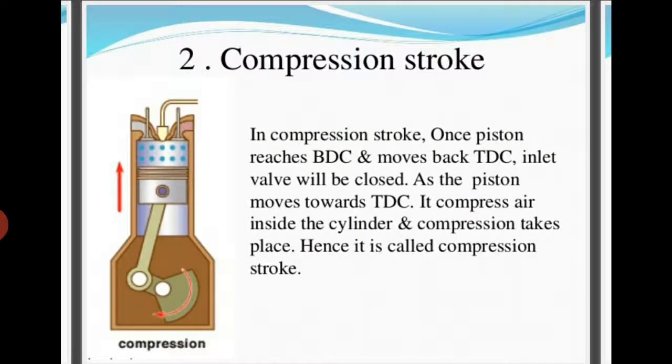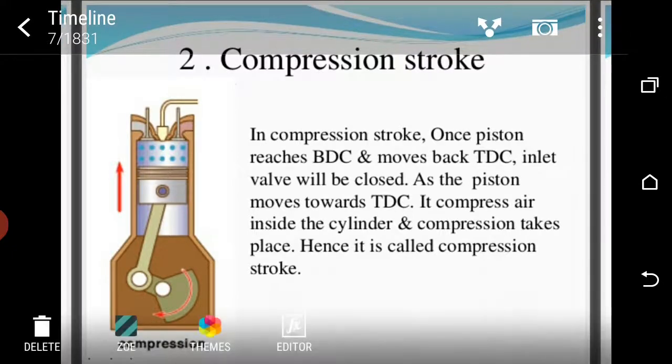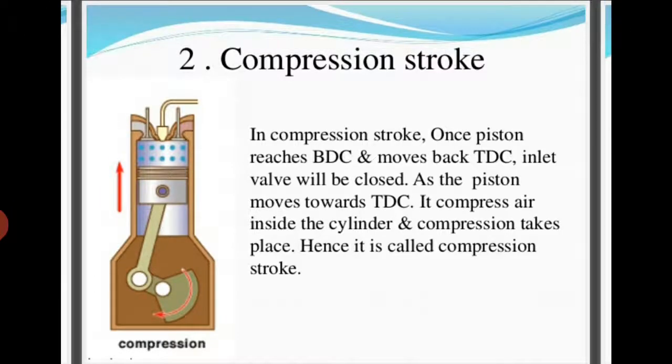In this stroke, both the inlet valve and the outlet valve are closed, and the piston moves from the lowermost bottom position to the topmost position, that is called the TDC position. Both the valves remain closed. The upward movement of the piston compresses the air to a very high pressure, about 40 to 45 bar, depending upon the design of the engine, and also increases the temperature of the air from room temperature to 650 degrees centigrade, which is very high to